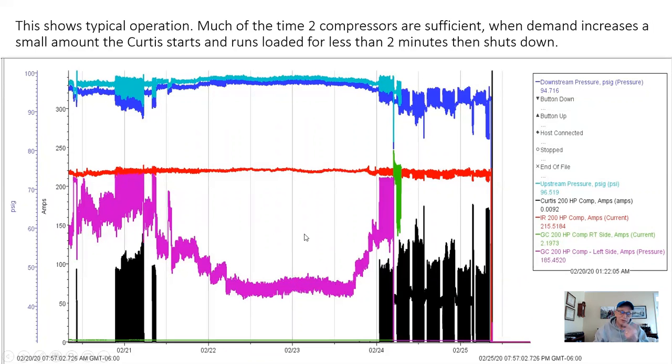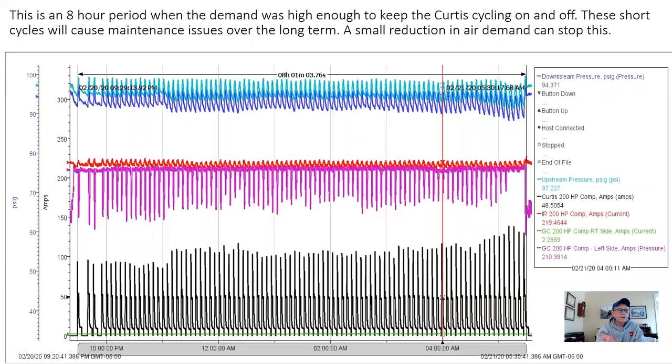So, another issue there, perhaps this Gardner-Denver could be put on automatic start-stop, and for periods such as this, when we get these drain traps changed out, that might be enough to eliminate the need for this. And that would be significant. I mean, that's a 60, 70 amp load that maybe could be shut down a bunch of times. So that's something else that could be discussed. I don't know that we can quantify that.